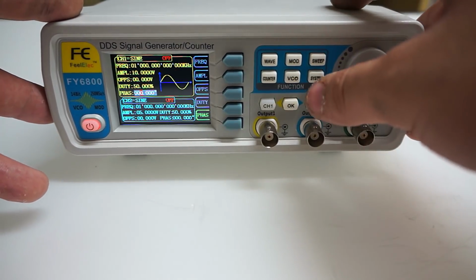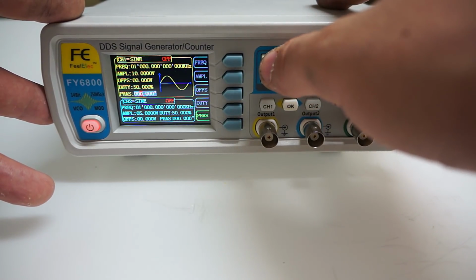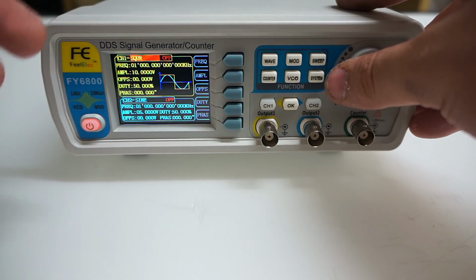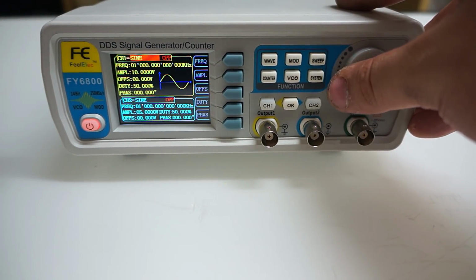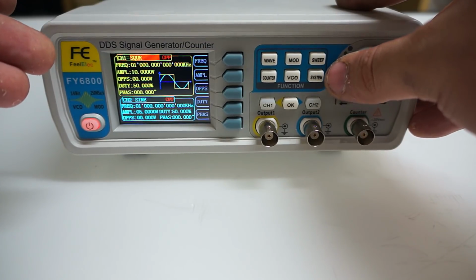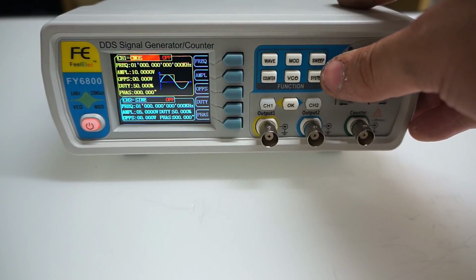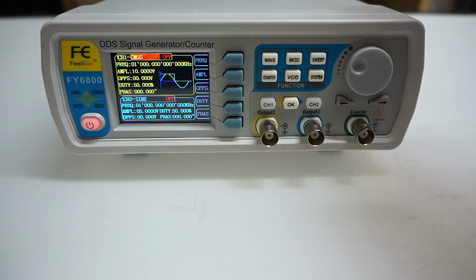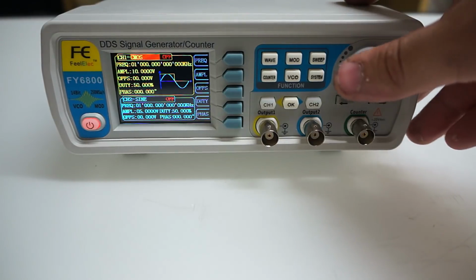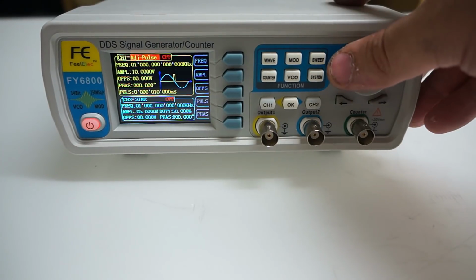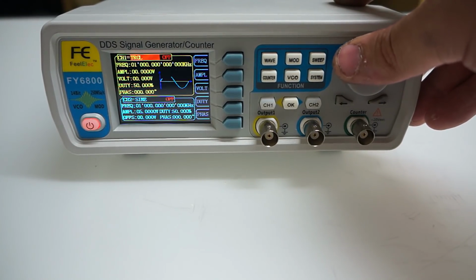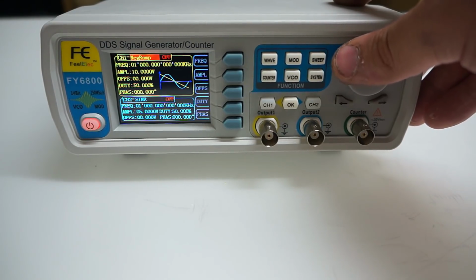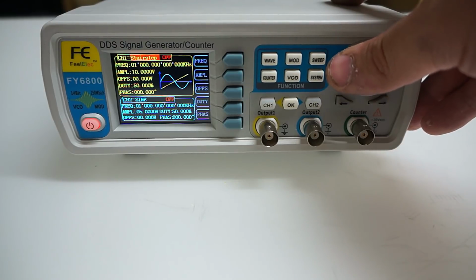On the right we have 6 buttons. First is the wave. If we click wave, we can change the waveform. It's standard, skips one forward, so if you go back one, we got a sine wave again. There is square wave, CMOS, which at the base is 0 volts, but goes up to the amplitude. An adjustable pulse, a DC voltage, a triangle, a ramp, an inverse ramp, a stepped triangle, a stepped ramp, a